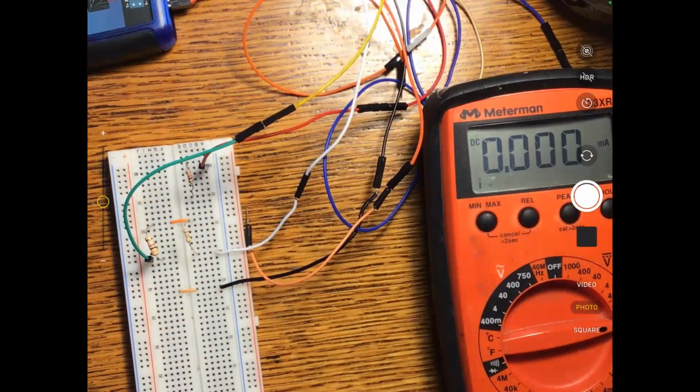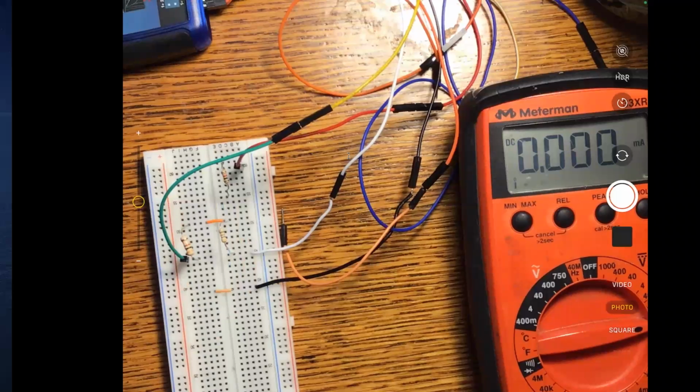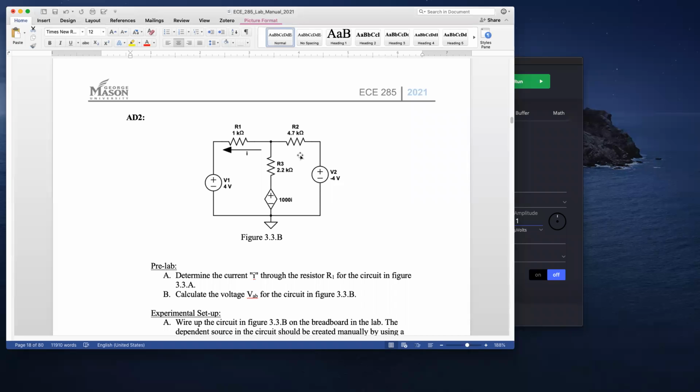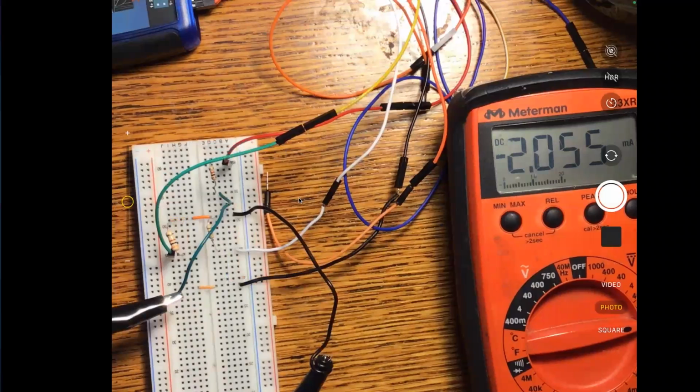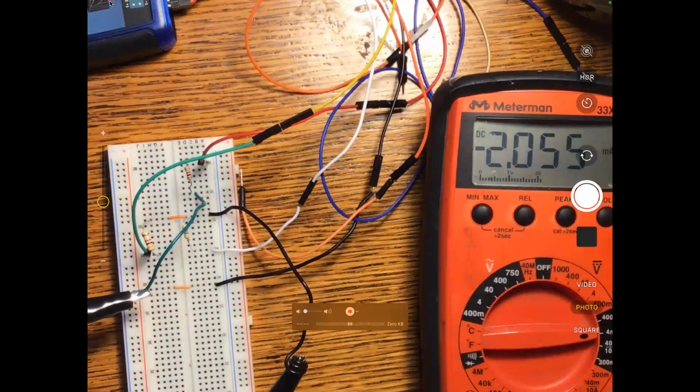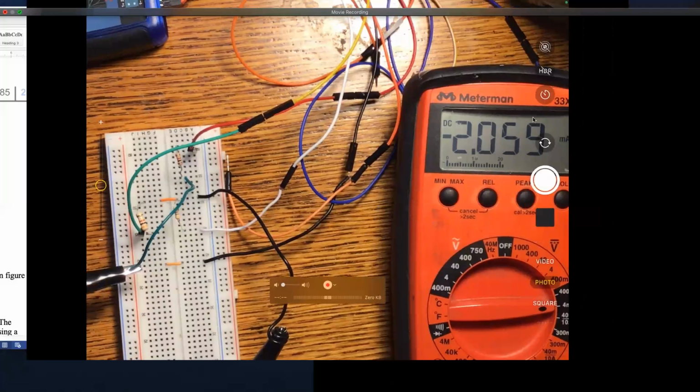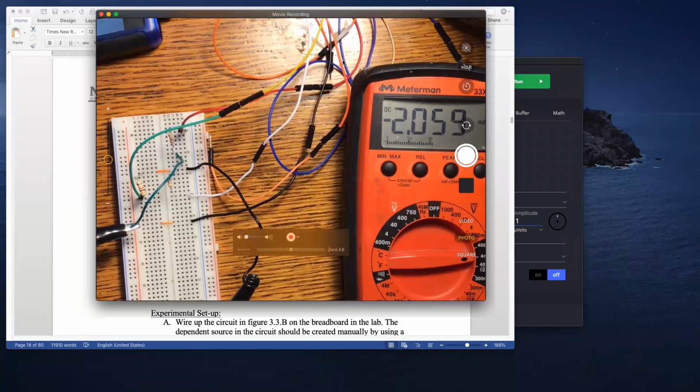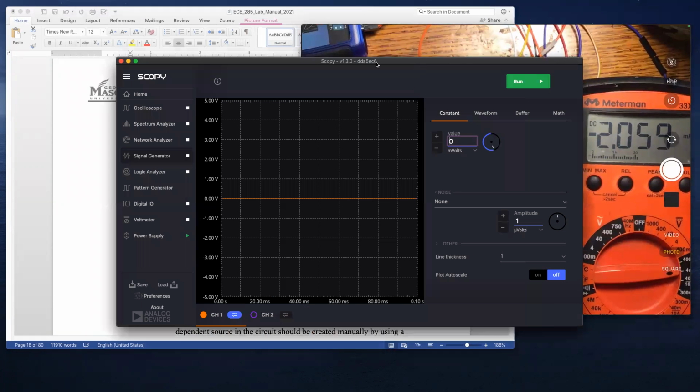But now I need to come in with my ammeter. You want to place the ammeter in the right orientation, so that you are measuring the correct current. Okay, so I have wired mine right. So it's going to be harder to do. Let me see. Okay, wonderful. So I'll have my current on the right side, have my voltage on the left.